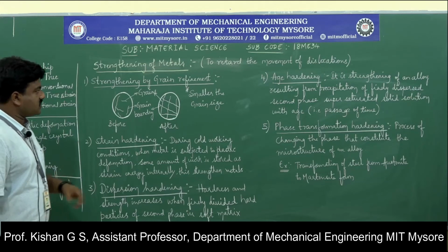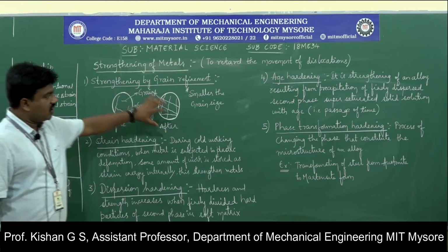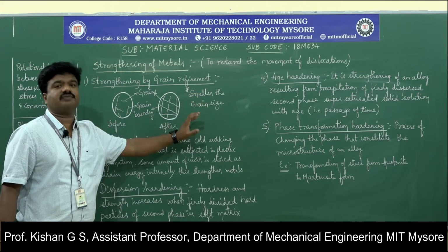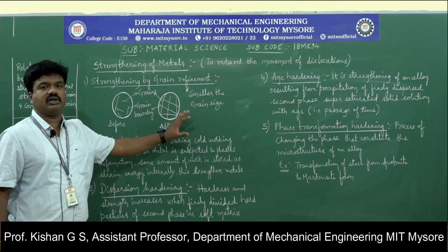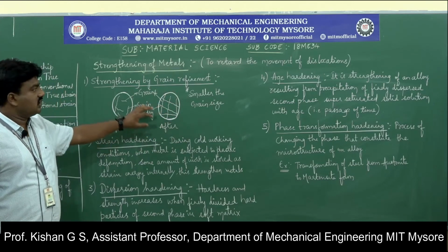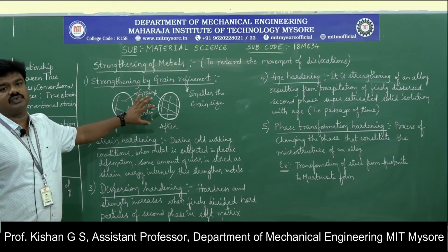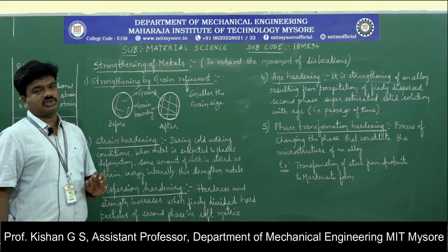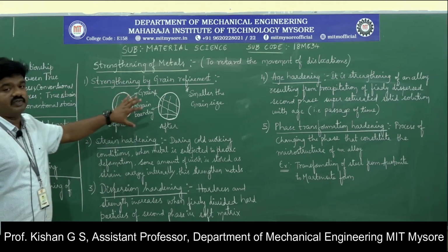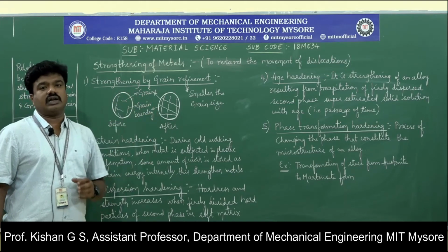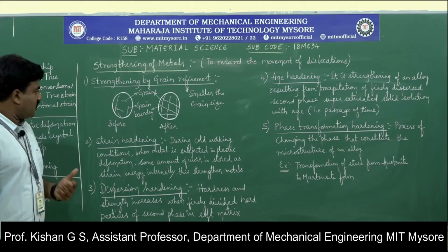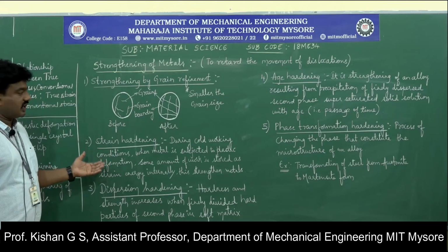So here, when we concentrate on reducing the size of grain, that results in better formation of grain boundary in any material, which results in increased hardness and strength of a material and thereby reduces the movement of dislocation. So this is a concept wherein we target the reduction in the grain size so that the strength of materials is enhanced. Followed by the next method, that is strain hardening.